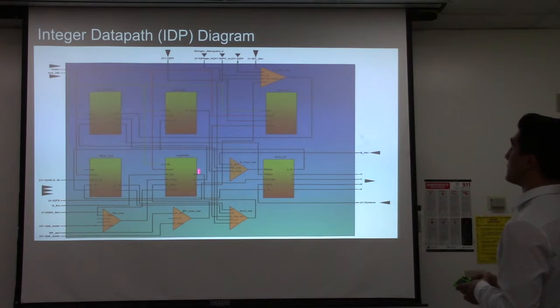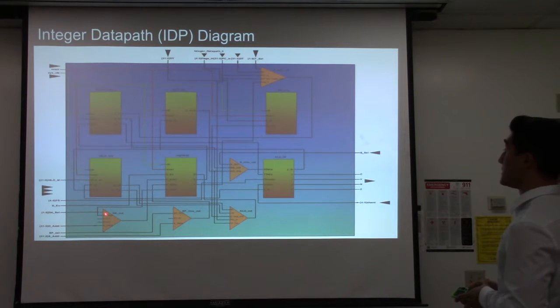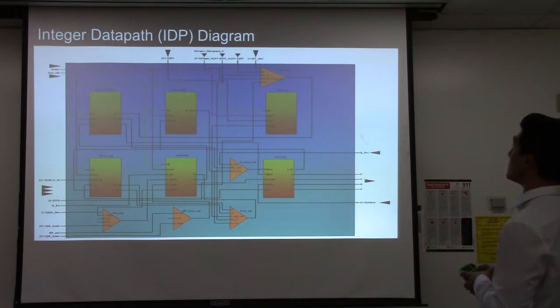And then we also have a T mux out over here, which selects what value of T gets sent into the DT over here, into our RSRT register. So instead of choosing something from a T address register from the reg file 32, we can just go straight into an immediate value or a PC value.